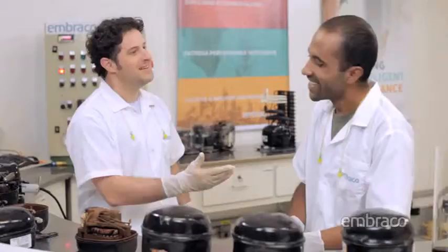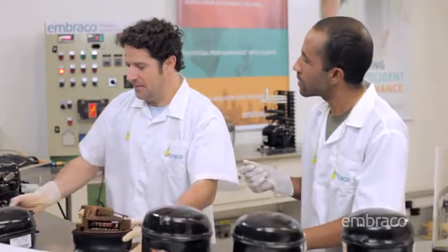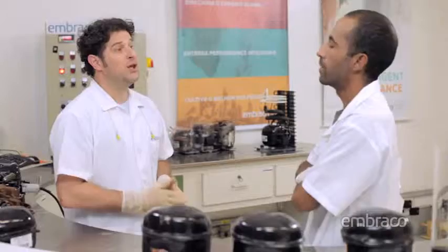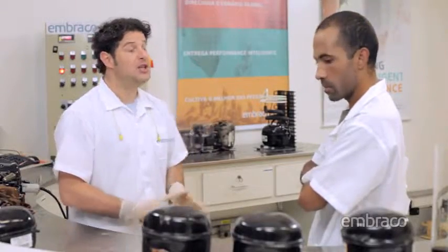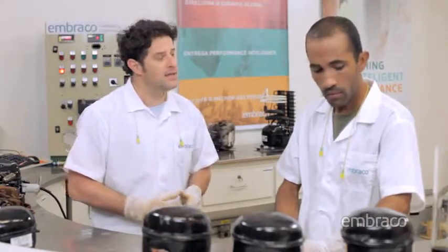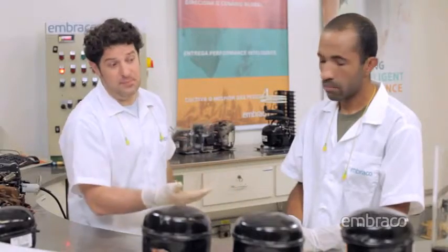That's right. Speaking of chemical reactions, I've heard of people adding antifreeze to the compressor. Can this cause a problem? Yes, Mark, the problem is that the antifreeze, being an alcoholic solution, as it's added to the cooling system, chemically reacts with plastic components inside the compressor, making them fragile and brittle, compromising their quality and durability. Furthermore, it may generate changes in the chemical composition of the oil, causing it to lose its lubricating capacity.